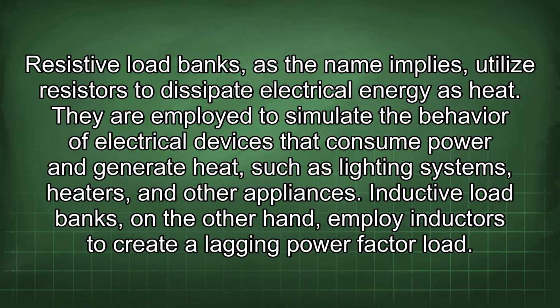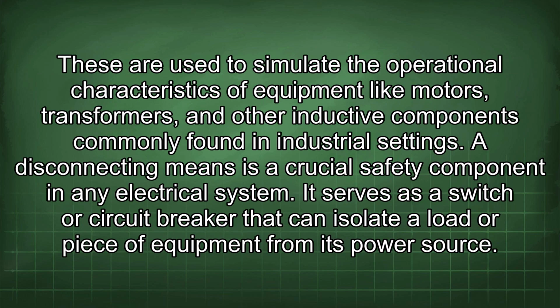Resistive load banks, as the name implies, utilize resistors to dissipate electrical energy as heat. They are employed to simulate the behavior of electrical devices that consume power and generate heat, such as lighting systems, heaters, and other appliances. Inductive load banks, on the other hand, employ inductors to create a lagging power factor load. These are used to simulate the operational characteristics of equipment like motors, transformers, and other inductive components commonly found in industrial settings.